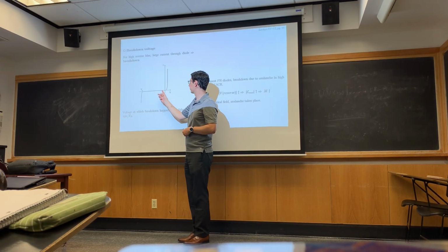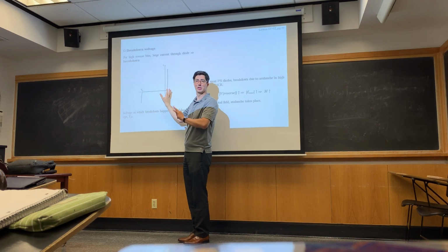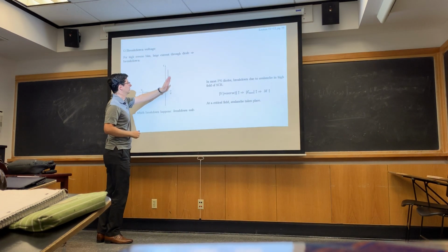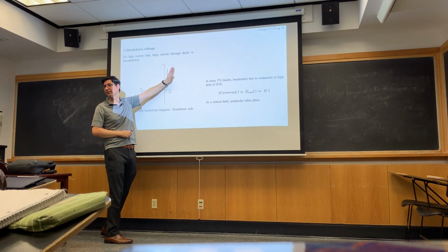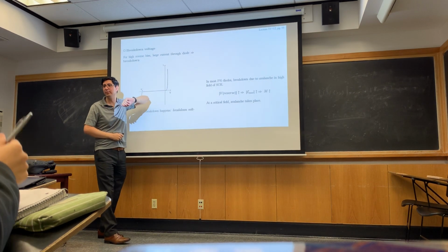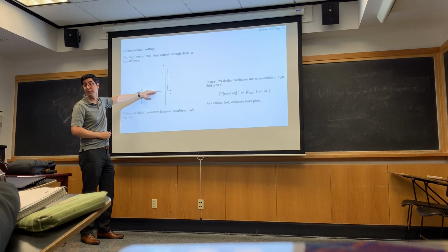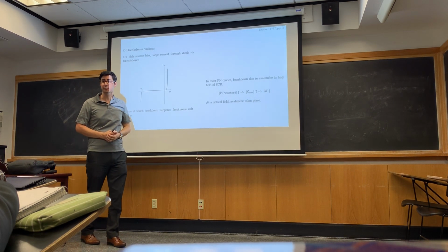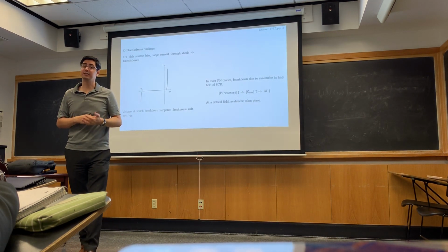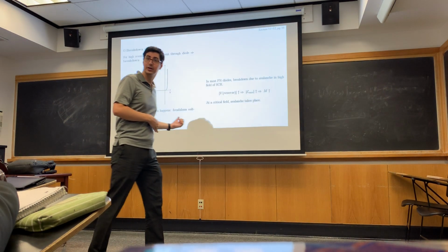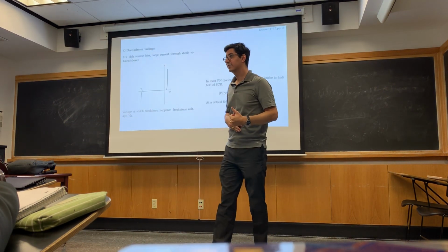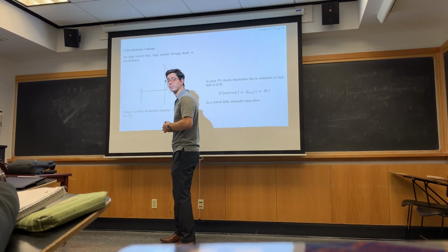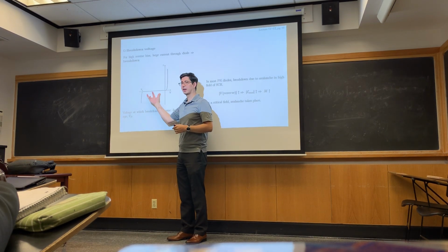So what's happening here? This is the forward bias part of the curve right here. And this is a really large scale, so all we're trying to see is, okay, the current is increasing exponentially in forward bias, it's just increasing so much it goes off the scale. In reverse bias, the current's very, very small. But at a large enough reverse bias, breakdown happens. Now you can design diodes intentionally to have this breakdown, and you can use this as an advantageous feature. Anybody have an idea what I could use this for? This breakdown?